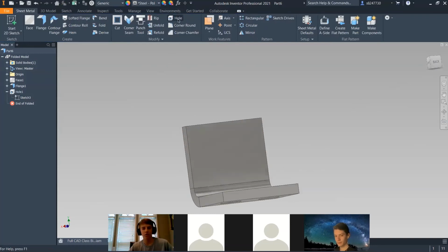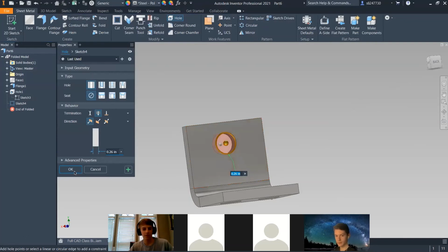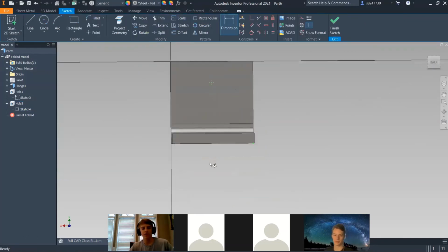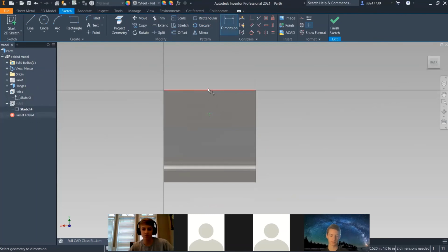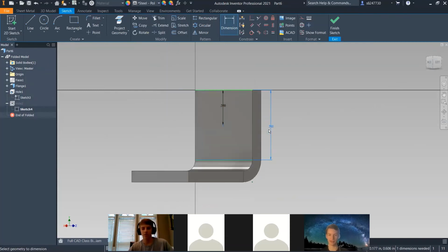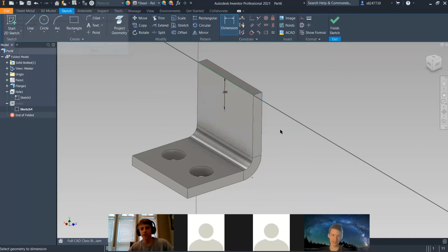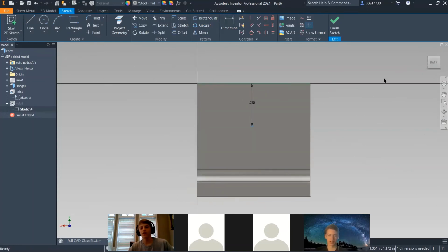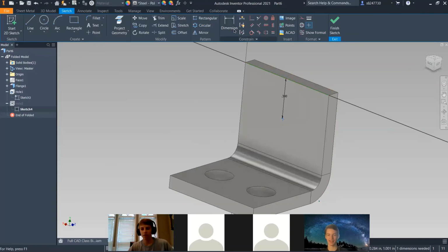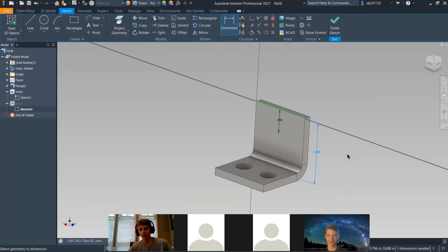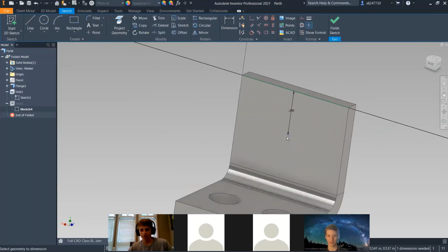So next, we're going to need another hole. It goes right here. This one will actually connect the arms to the piece. So here, 0.76. The reason I'm doing 0.76 is because the distance from here to here, showing in 3D, is 0.76. So this is in the middle of that spot. Even though it's not in the middle for 1 inch, in real life, it'll look like it's in the middle because it's just an observation.